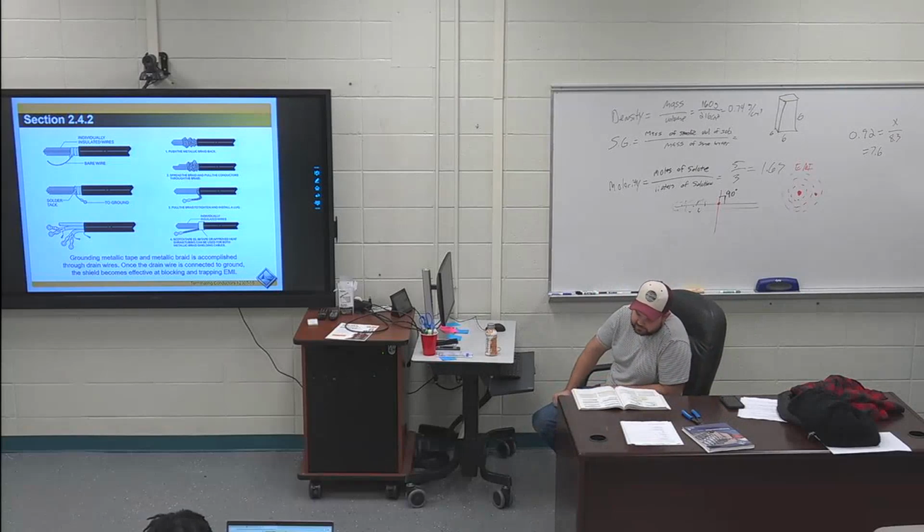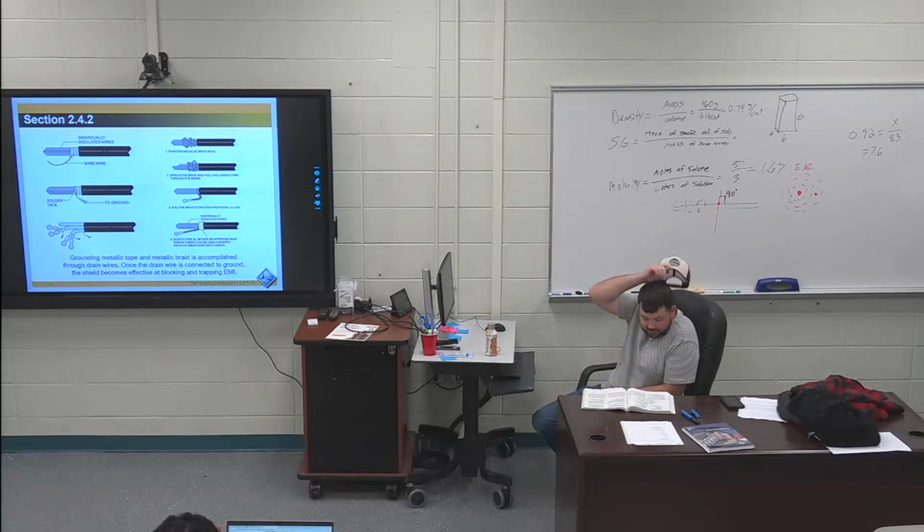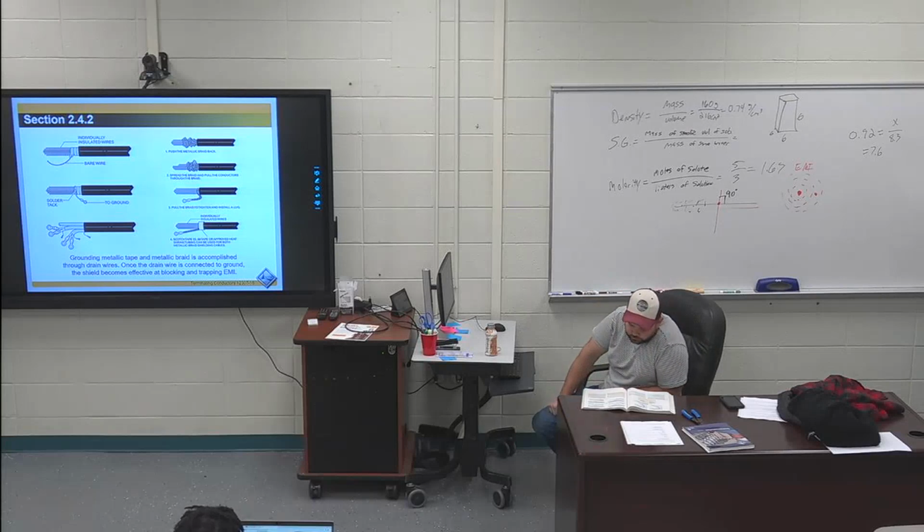Terminating typical shielded cable. Second paragraph, the whole second paragraph of 242 is highlighted. If the shield or drain wire could possibly come in contact with other shields or drain wires, terminal block points, equipment or equipment cabinets, they should be insulated with insulated tubing or heat shrink tubing to prevent short circuits and circulating currents. A cable that has individually shielded conductors with separate drain wires must have each drain wire and shield tape insulated to eliminate possible circulating currents.